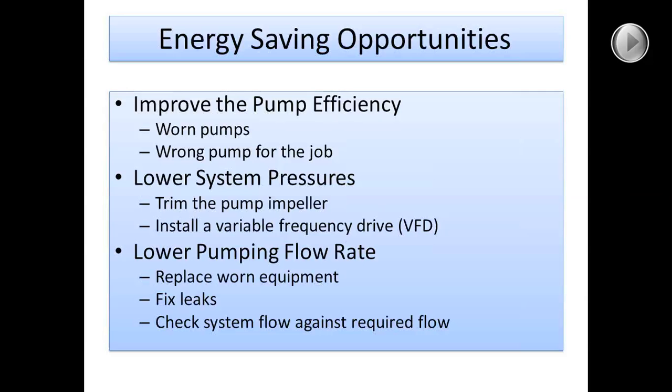Another big opportunity for efficiency improvements is if the wrong pump is being used for the job it's doing. I've seen this in several different ways. One system that we just looked at recently had several deep well pumps, and at each wellhead they had a booster pump as well. The system was designed to operate with the well and booster, so the well would just lift the water to the surface, probably at 5 psi, and then the booster would boost it to 60 psi, the system operating pressure.